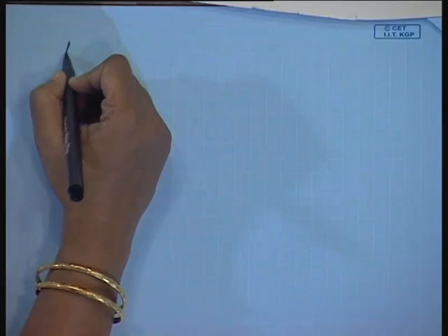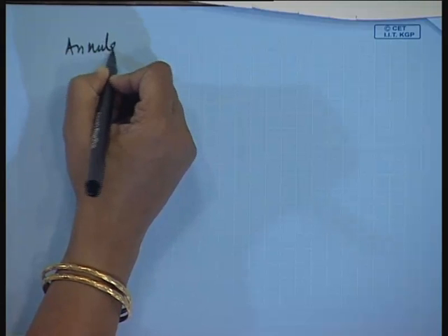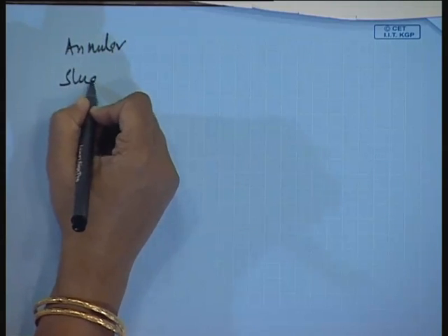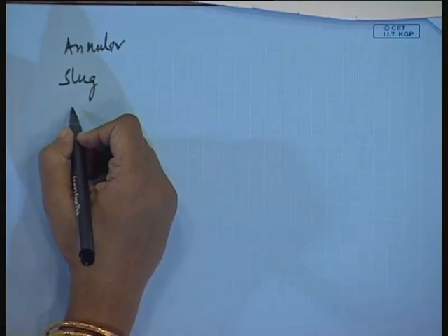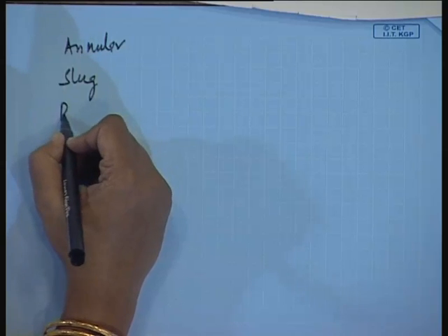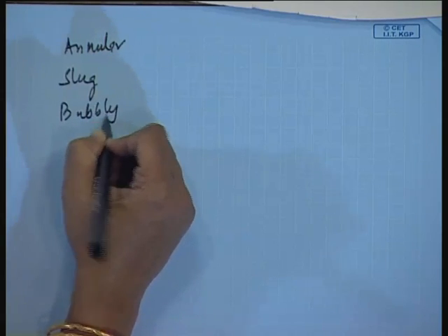We are taking gas-liquid flow for the time being, and the same things apply for other pairs of fluids as well. Okay. What are the different flow patterns that we encounter in horizontal flow? Louder? Annular, slug, we definitely get. We will get annular flow pattern, slug flow pattern, bubbly, let me write down first, okay.